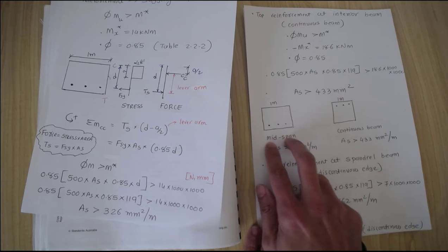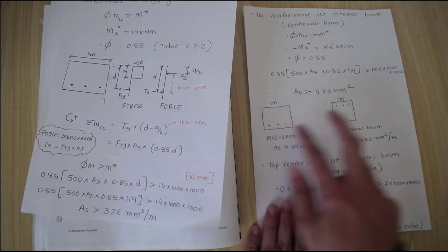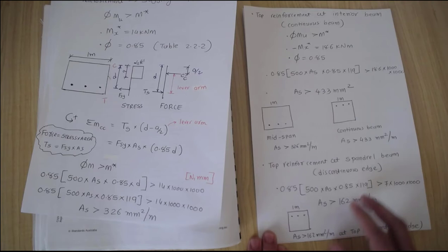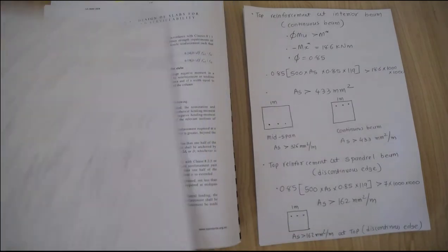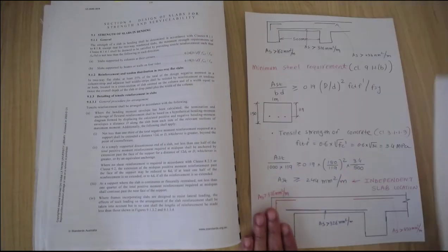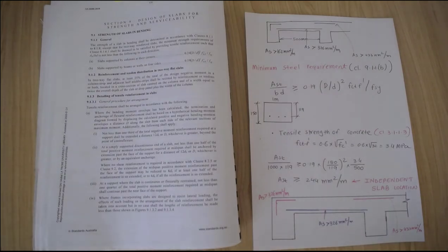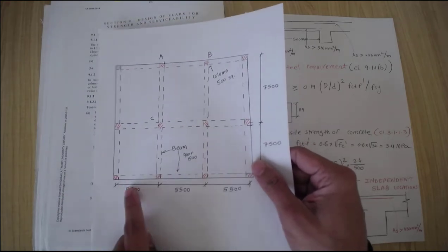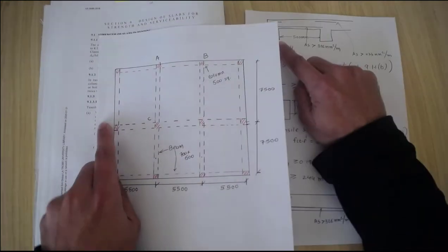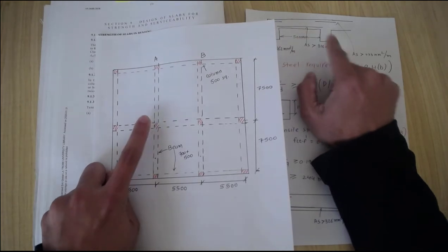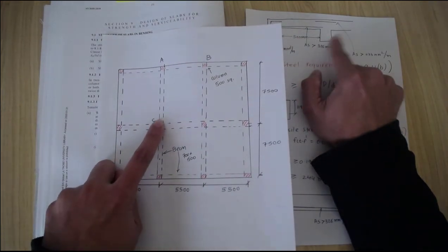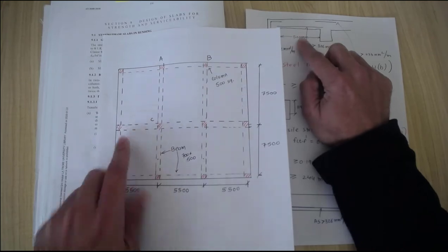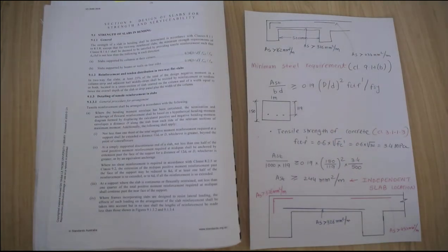So at midspan we provide the bottom tensile reinforcement, at the supports we provide the top reinforcement here, and this is also again at that discontinuous edge. Now there is one more requirement that I would like to emphasize. Let me redraw these pictures. Looking from this side, 5 meters, I redraw this beam here, then you have this span, and this beam that I draw, and then you have the continuous support. We are working on this one, so I put those notes here that we just calculated.